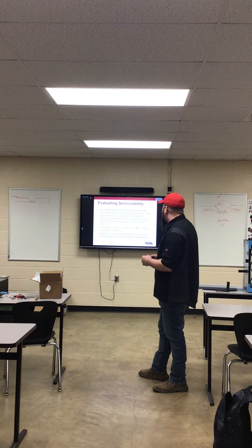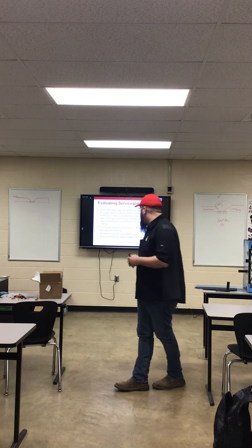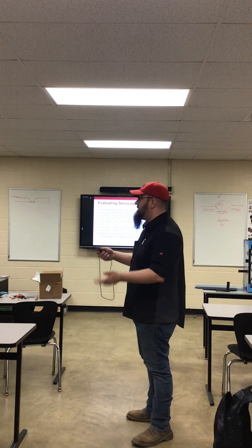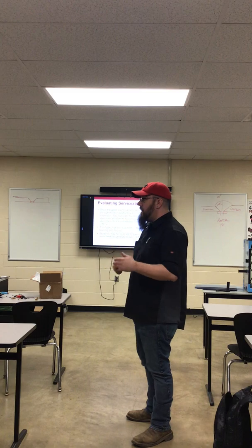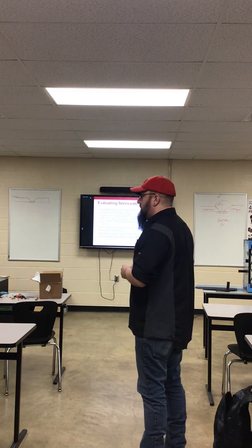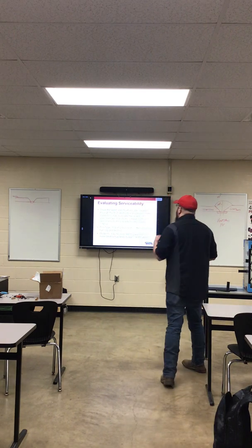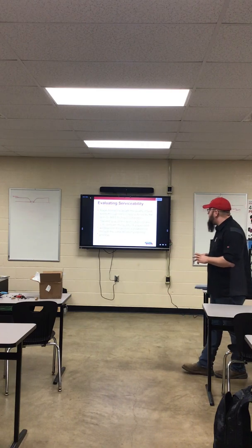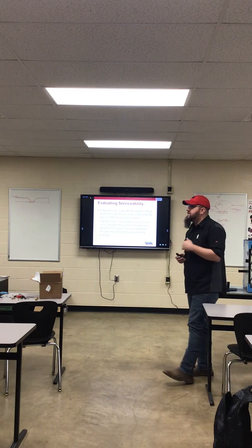This type of destructive test is often used in training and testing. Students may be required to pass one or more destructive tests to earn certification. Our AWS D1.1, you have to pass just one. Whether it's fillet weld, groove weld, flat, horizontal, vertical, MIG, TIG, stick, flux-cored, it works. Now, inspectors will evaluate the quality of the test welds through the process outlined by the specific AWS testing procedures.